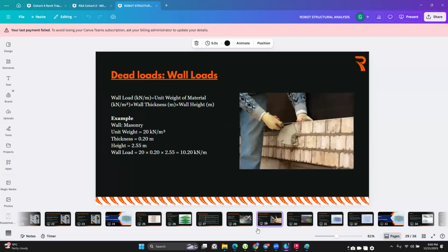So I'm going to use 1,000. 1.5 is too large. Probably it's too high. It's usually around 900 if you look carefully. So let's go with 1.2 then. We are going to multiply the 1.2 times 20 times 0.2, the thickness, and you're going to get 4.8 kilonewtons per meter. You can see it's even less than half this load, so there is no need of having such an over design.